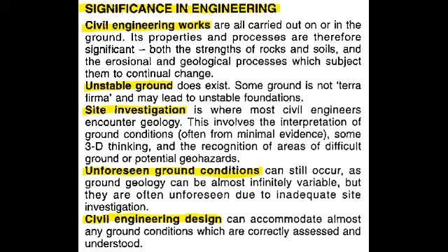Site investigation is where most civil engineers encounter geology. This involves the interpretation of ground conditions, often from minimal evidence, some 3D thinking, and the recognition of areas of difficult ground or potential geohazards. Unforeseen ground conditions can still occur, as ground geology can be almost infinitely variable, but they are often unforeseen due to inadequate site investigation. Civil engineering design can accommodate almost any ground conditions which are correctly assessed and understood.